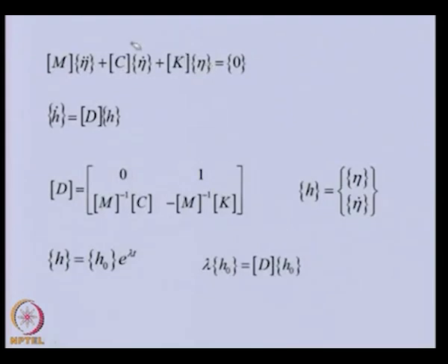Now, as compared to the previous case, earlier there was minus omega g for the gyroscopic couple case. Now, in place of that, c has come. So, the state space formulation will be exactly the same; the only thing is that in this particular D matrix, minus omega g will be replaced by c.